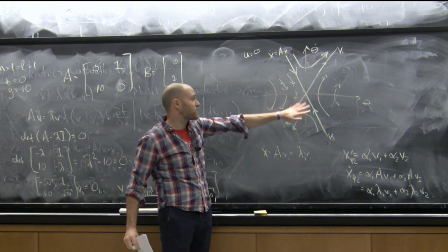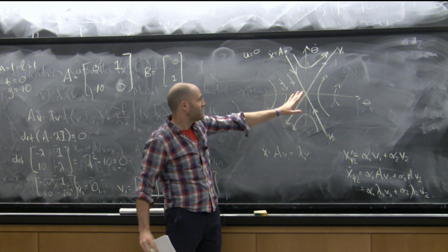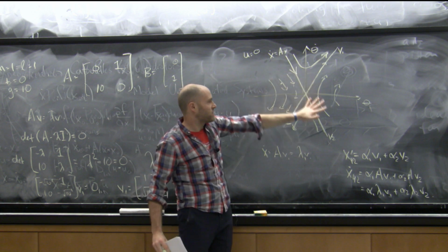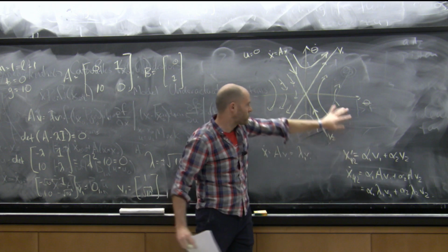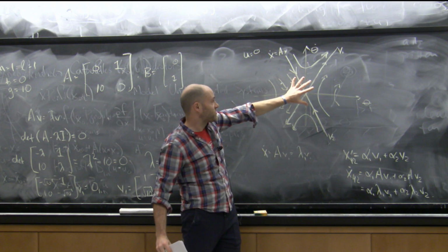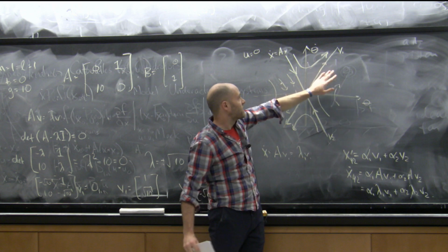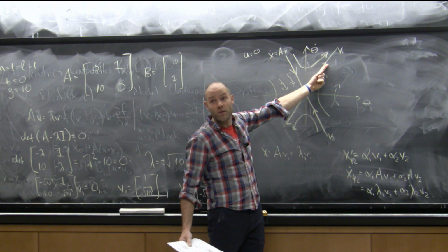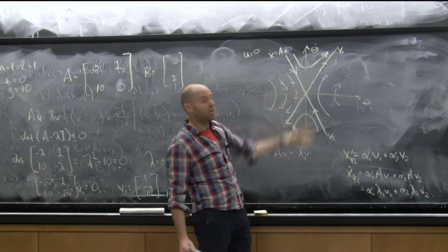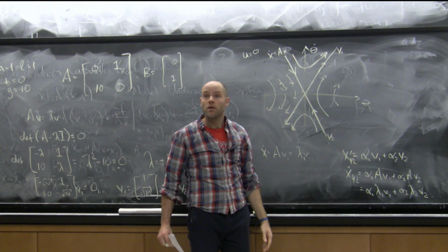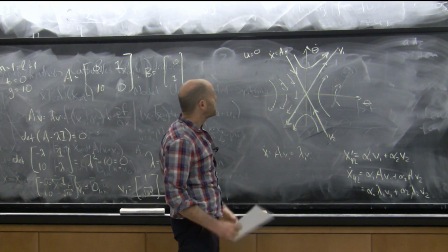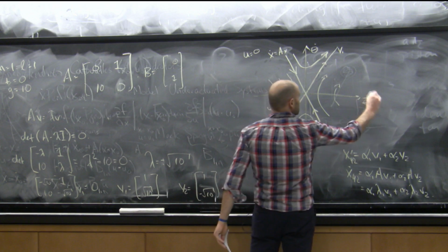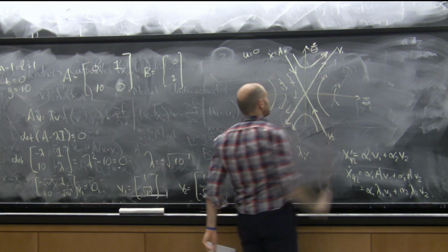I've linearized the dynamics of the pendulum around the upright, and I've just drawn the vector field just like we did of the pendulum. This is just a different set of tools for finding out how to draw those arrows. But this is still just the same diagram, which is for every theta, theta dot, I'm drawing the vector, which is the direction that that thing wants to flow when I'm in that state, right? And this is what the picture looks like. These should be theta bars and x bars and stuff like that, right? Correct. This is all in the relative coordinates. Thank you. I should be less sloppy about that.